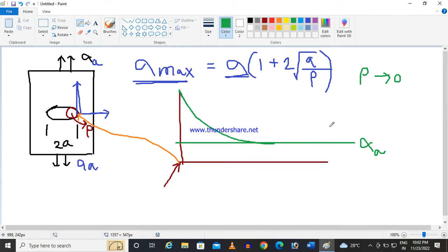So this concept is very important to understand crack propagation. That means if there is a notch in the crack, the stress concentration is very high. That's why, if you see in the locomotives or in the aircraft, the openings, the windows, if you keep them rectangular, what will happen?